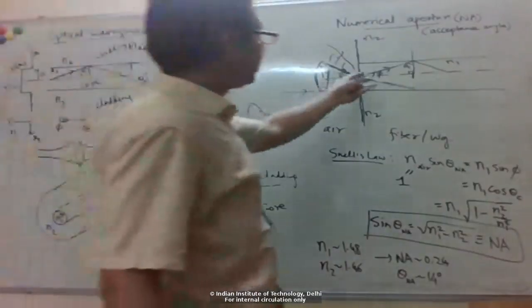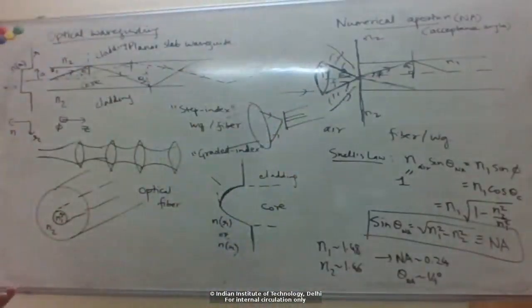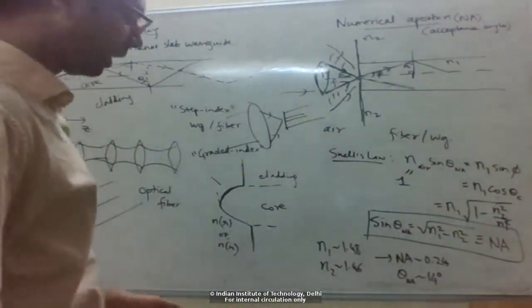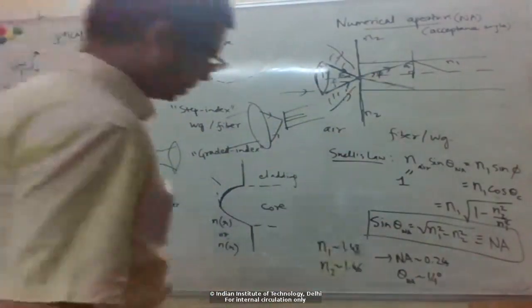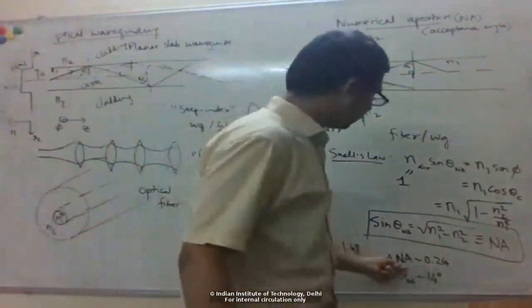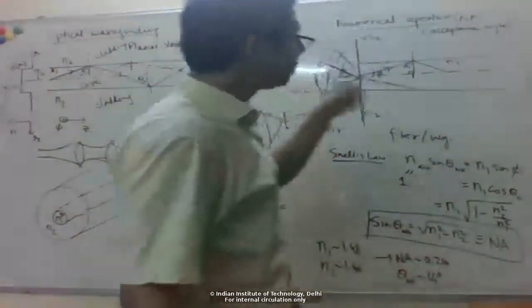So this ray picture is valid when the fiber is highly multimode, which means basically that in the mode picture, it's supporting a lot of modes. We'll discuss what modes are exactly later, but in the end, what I'm trying to say is that typically fibers are very small in NA. Okay, so this 0.24 is for highly multimode fiber, which is sort of the upper end.